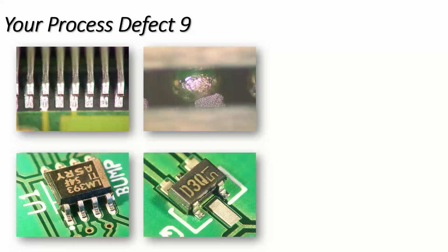If I may, just go on to one other point. I have a lot of issues sometimes with customers not allowing modifications to a design. And the classic one is hole to lead ratio, for intrusive reflow, selective soldering, wave soldering, solder shorts, all these sorts of things. Just by getting the hole to lead ratio right, rather than following what the connector manufacturer said on their data sheet, which 9 times out of 10 is not right, that can improve yield, functionality and reliability.